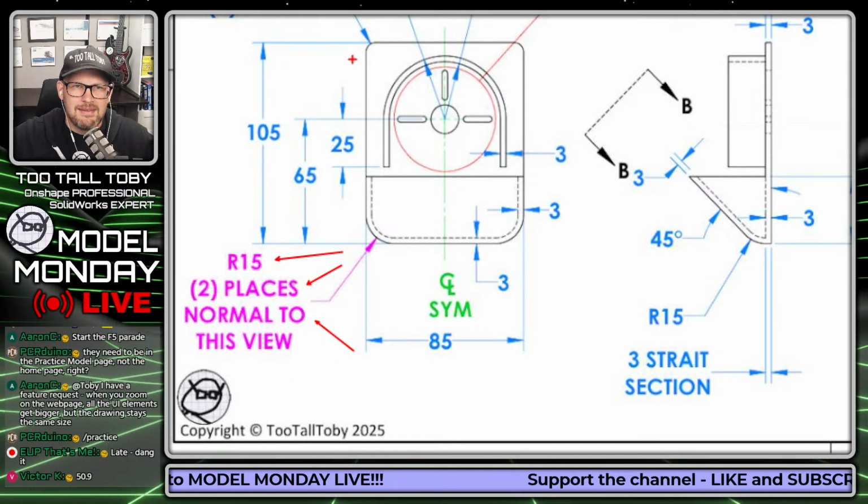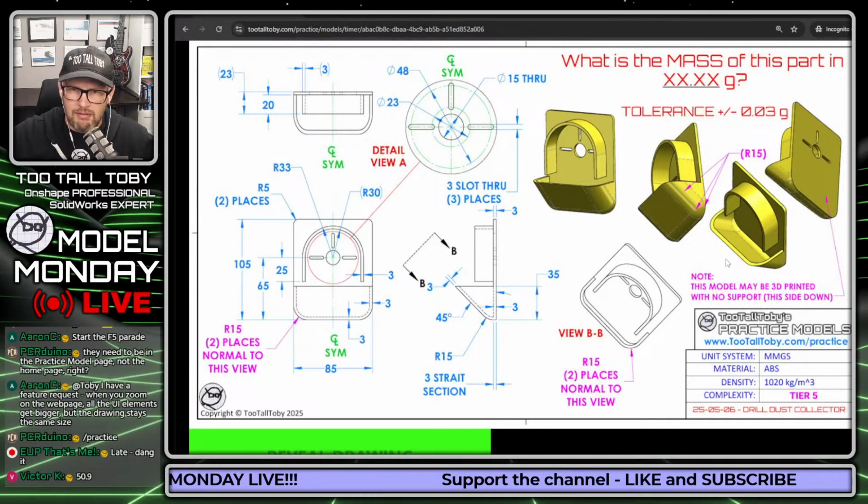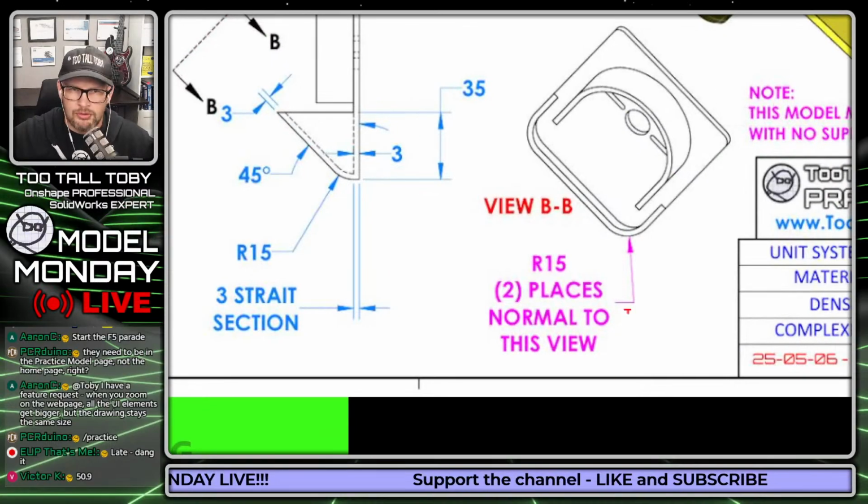And so what that means is that if we're looking at this thing dead on, this radius here is a true radius of 15. However, you can also see that that radius of 15 is being called out normal to this view here, which is at our 45 degrees.